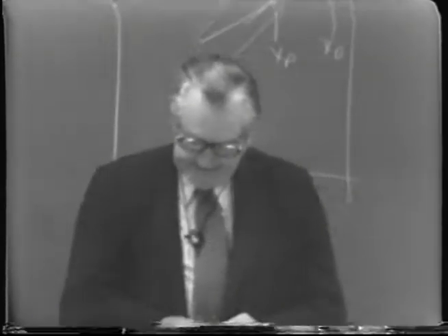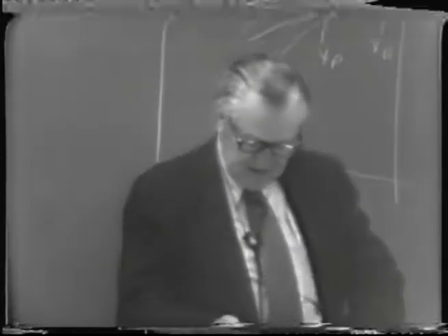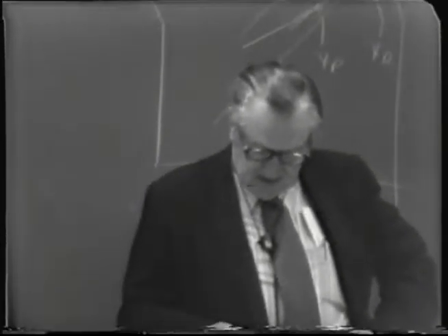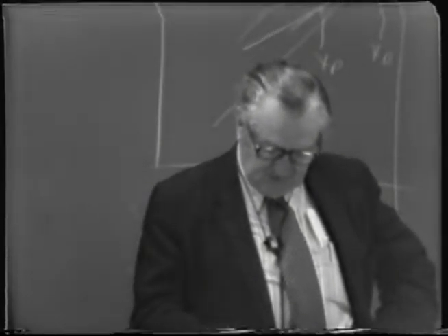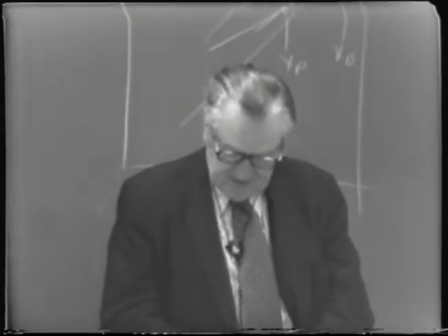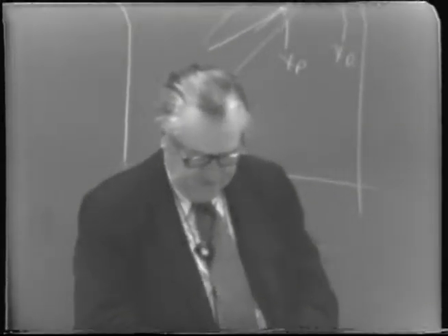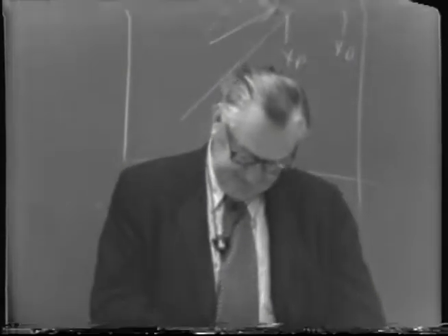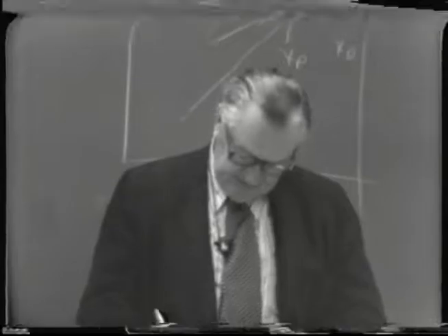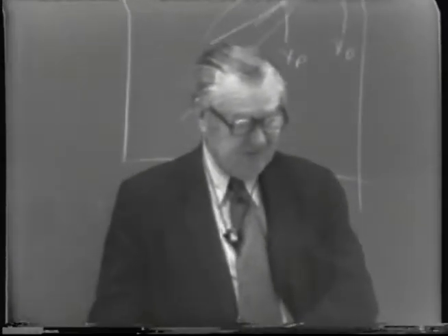Then locating the conditions for the stripping section on this little side chart here. The way I do that is to locate, of course, the Q line, draw the Q line in, and then draw in a little bit of the lower part of the operating line for the rectifying section in order to find the point of intersection.